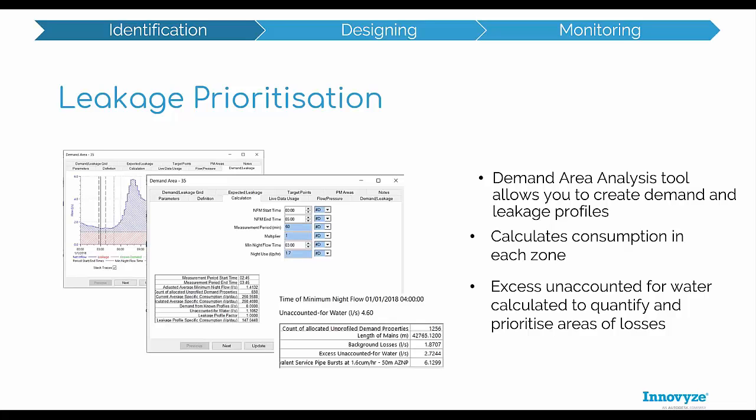And so by doing the demand calculations within the model, often those are done externally in spreadsheets, but we're using those live data connections, and any changes that are made to the network configuration, the demand can be easily recalculated. If you would like to do the demand for another period of time, you can easily change the day, and the new demand and leakage curves can be calculated.